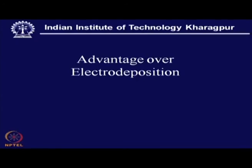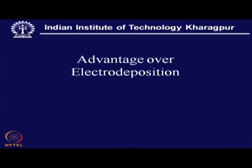And the advantage of this electro-less over electro deposition is that, in this case we do not need any electricity, you have a better uniformity of deposition, a substrate need not be conducting, and we can have a densification of the coating. So, these are a few advantages one can immediately extract from this electro-less process. Only one limitation is that the surface of the substrate should be autocatalytic in nature.